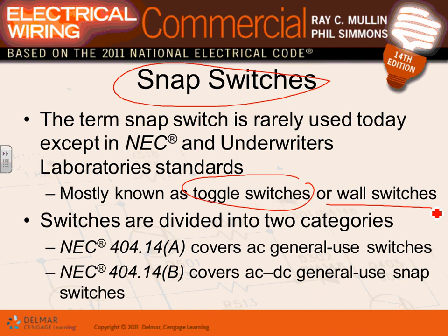Switches that are so cheap that I can put in my basement for 33 cents or 50 cents. And the ones that engineering firms specify, not the cheap residential type. They call them spec type devices, spec type receptacles. They're bigger, more robust. They can handle the interruption of the current better. Same 15 or 20 amp switch. One of them will be cheap, typically made for residential. The other one will be more robust, a little bit more expensive, made for commercial and industrial. They do the same function, and they're all 15 or 20 amp switches.